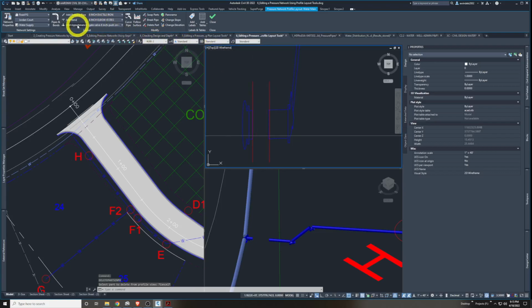Now let's add an appurtenance. In this case, let's see what we got. It doesn't even really tell us which appurtenance to pick, but there's only really one here. It's a gate valve, 6-inch of certain PSI pressure rating by the AWWA, which is American Waterworks Association, different ratings.